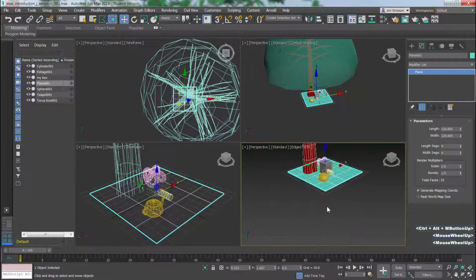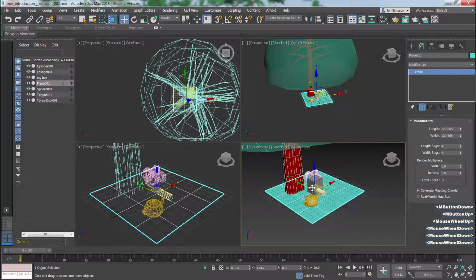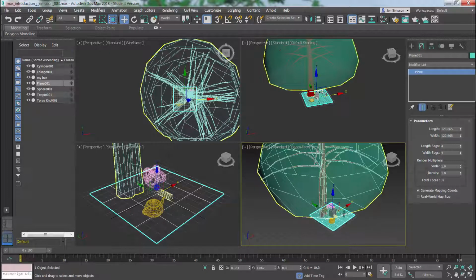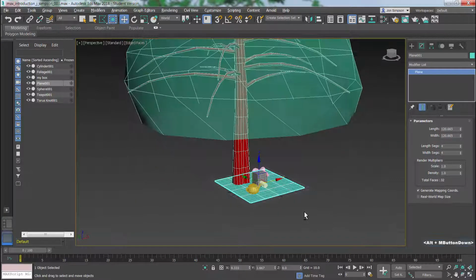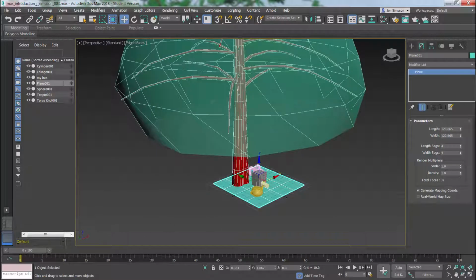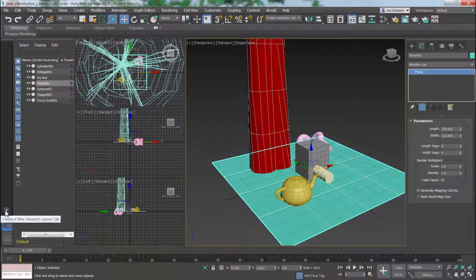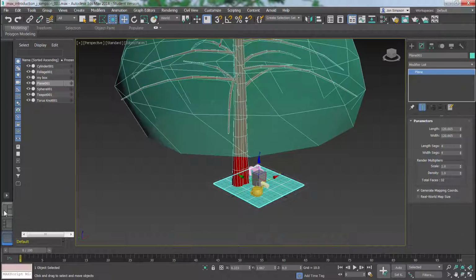These are the basic controls. There are many more shortcuts to learn along the way. To maximize the active viewport, press Alt-W. In the Viewport Layout tab, I can choose from preset view layouts to have open in tabs to quickly switch between them. These take up RAM. The more you have open, the more memory you will want to have.